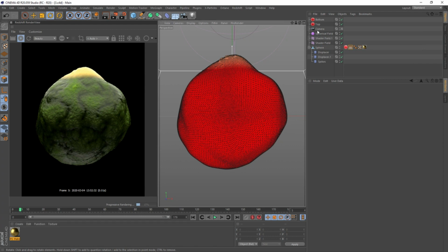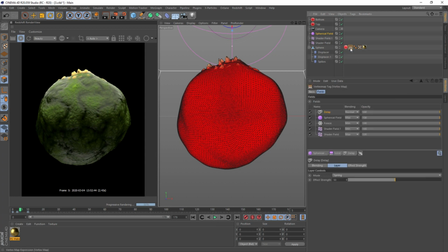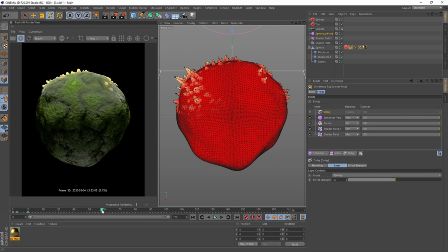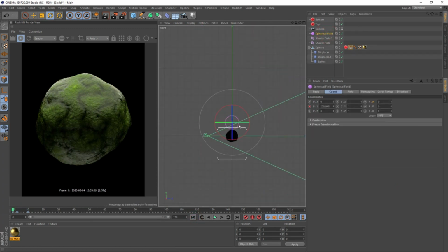We're going to our sphere. We disable all animation in X and Z position and all the scale and rotation. I use holding Ctrl Shift and left click. So left click adds a keyframe, Ctrl Shift removes. And in fields, I add delay back before render. Let me disable it for faster preview. And I put our sphere to the back.